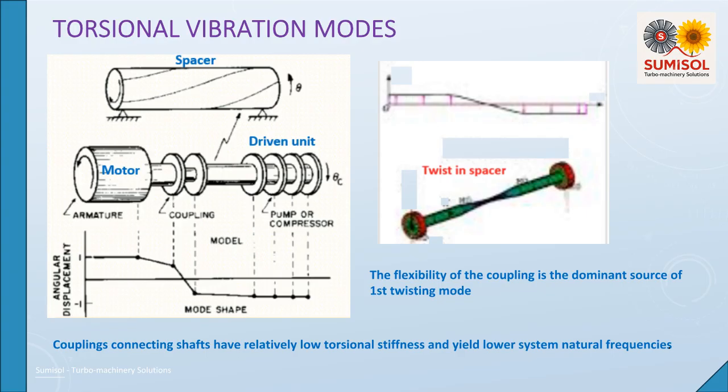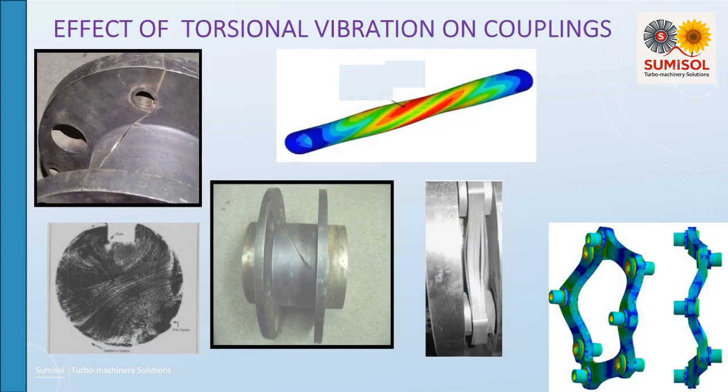often involving flexible couplings. Torsional vibration causes significant stress, overheating, and premature failure in couplings by introducing alternating torque spikes, which can lead to disc pack shims deformation, fatigue-induced fractures. These vibrations often cause catastrophic, rapid failures if the system operates near a torsional natural frequency.